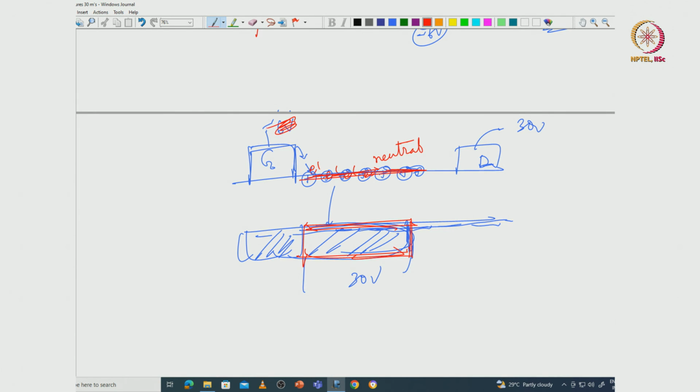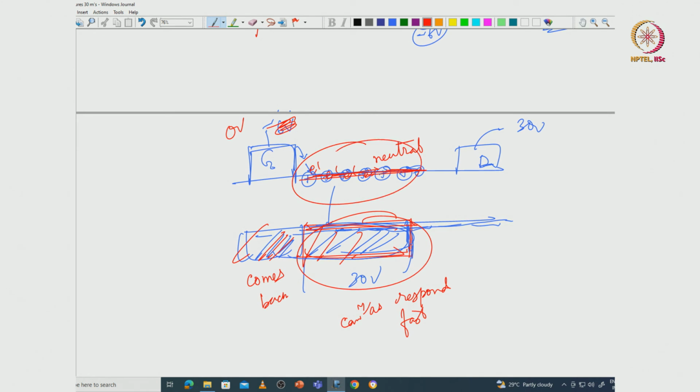Now when you go back from -6 to 0 volt, when you turn the channel on, this part is no longer depleted, the 2DEG comes back here. However this part here may not be able to respond as fast. Why can it not respond as fast? That is because these traps on the surface, to give the electrons back again and become positively charged donors, will take certain time. That is point number 1. The surface states will take a certain finite amount of time to actually give the electrons back and come back again as positively charged donors, and so the coming back of the 2D electron gas here will also take some time.